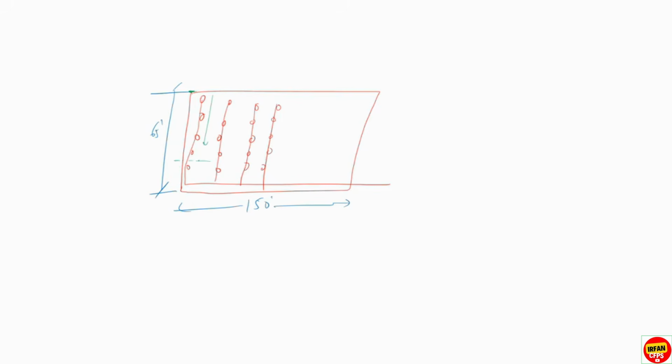Okay, so 46.47, for example, it comes here. So just mark it 46.47 feet. And then see, always remember sprinkler coverage will be in this way. Halfway this side, halfway this side. So always remember this point. The coverage area, we will consider half this way. So total length will be like this.